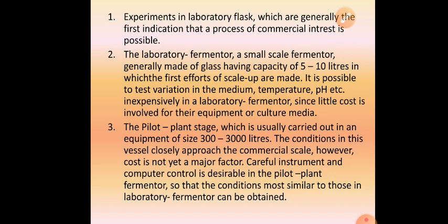Right. After laboratory fermenter, we go to a pilot plant stage. Then comes the pilot plant stage, which is usually carried out in an equipment having a volume of 300 to 3000 liters. The conditions in this pilot plant vessel closely resemble or closely approach the conditions that exist in a large scale commercial fermenter.